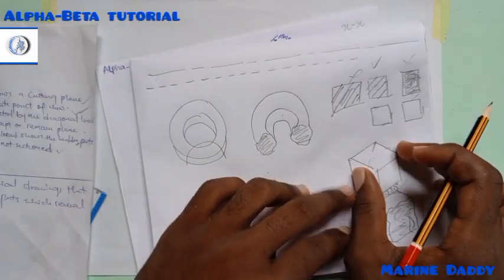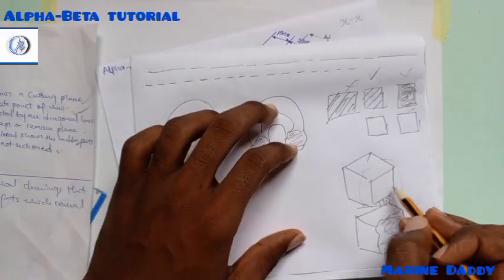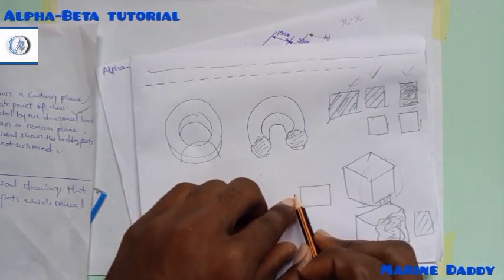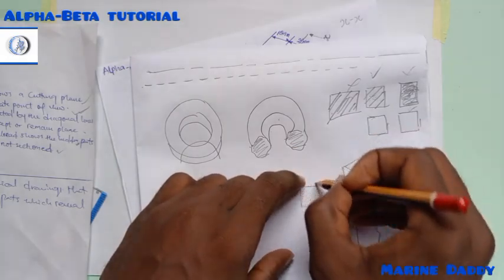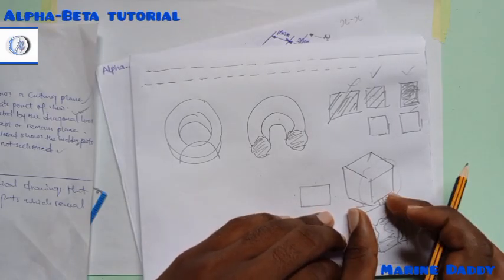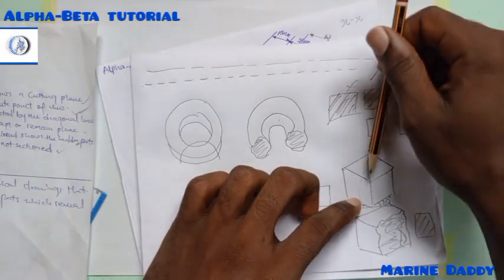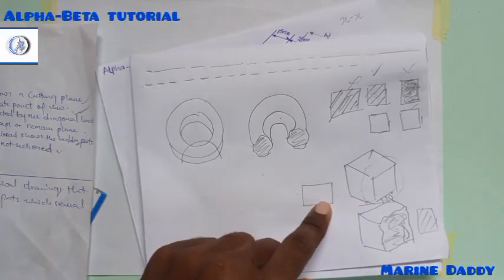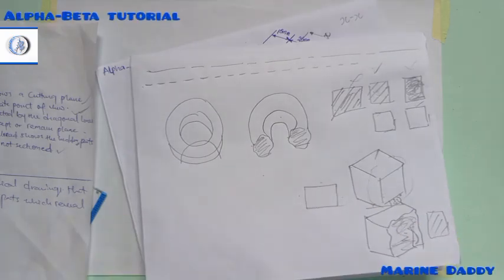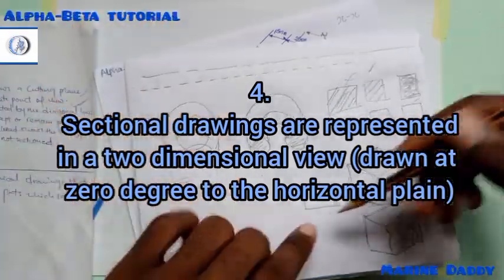Meaning that this diagram, if I were to identify this thing in a sectional pattern, is supposed to be laying flat like this, meaning I will not be able to see what is at this side and what is at this side, as well as this part. The reason why we present a diagram at 30 degrees for isometric drawing is so we can be able to see the front view, the side view, and the top view. But with sectioning, you don't have that privilege, right? Because it's just 0 degree. Now, back to what I was trying to explain. The positioning of a sectional view is 0 degree.